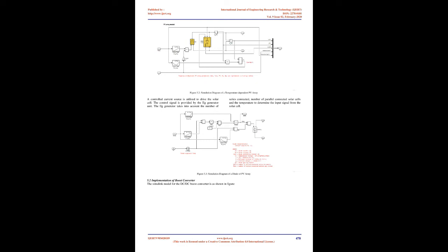3.1.1 Perturb and Observe method. This method is the most common. In this method very few sensors are utilized. The operating voltage is sampled and the algorithm changes the operating voltage in the required direction and samples again. If dP/dV is positive, then the algorithm increases the voltage value towards the MPP until dP/dV is negative. This iteration is continued until the algorithm finally reaches the MPP.